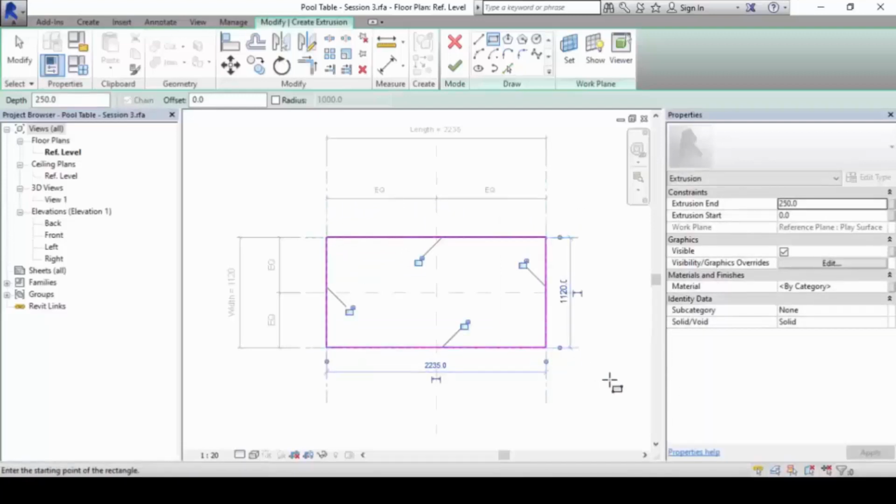Before we finish off the command, we will activate the constraints to lock it, so that when we flex the model to make it bigger or smaller, etc., it will also grow bigger or grow smaller. Can we understand this? If you do not lock it, when it grows, the size remains the same. So no effect, no use. Alright? So then we click Finish.